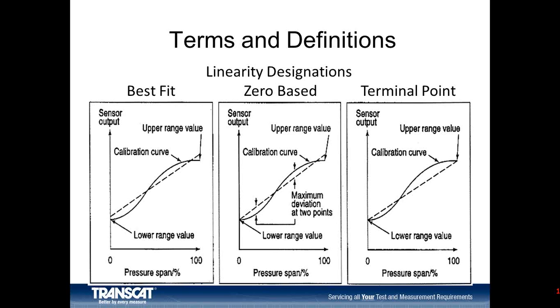On the left side, labeled best fit, some call this a best fit straight line, in some specifications BSFL. In the kind of a summary representation of the response of the test instrument, it's a trend through the data, does not correspond to any particular point along the way. It's only a best straight line fit.